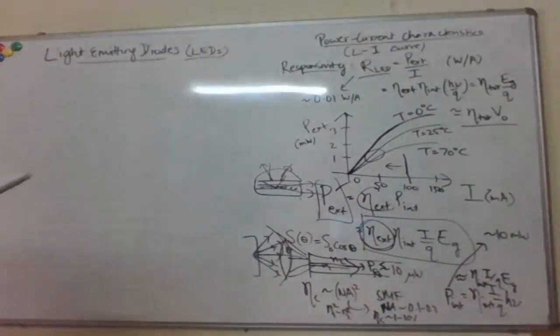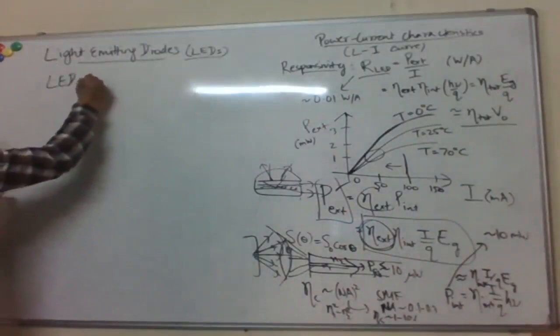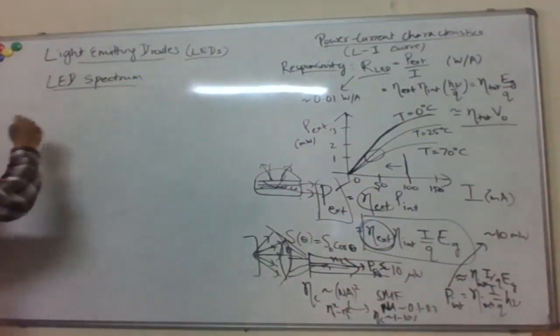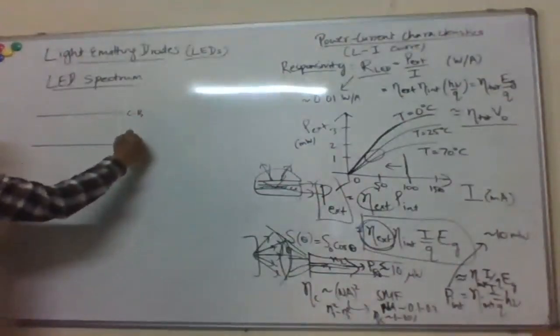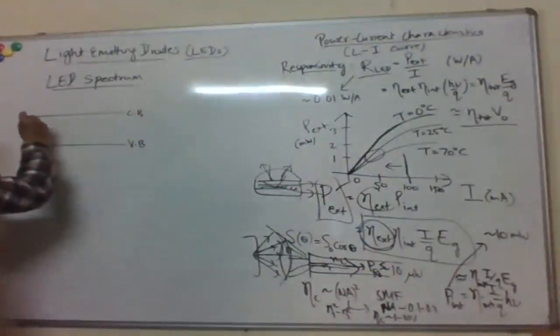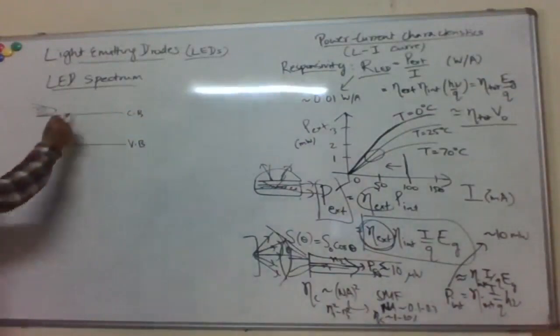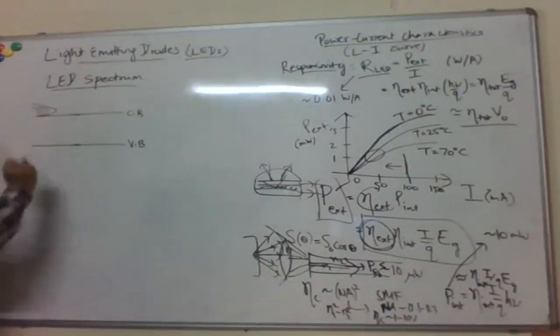Right, and this spread, recall, is coming from... so if you again look at the conduction band and the valence band, the carriers occupy some range of energy levels here. It is not that all of them were here and all the holes were here, and the recombination happened exactly from the bottom of the conduction band to the top of the valence band. In that case, it would be exactly Eg.